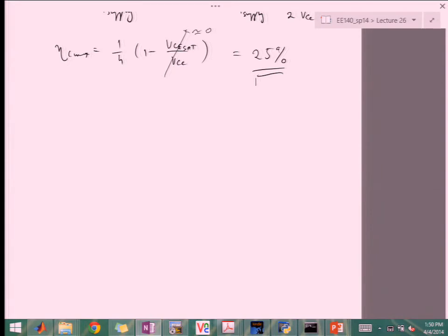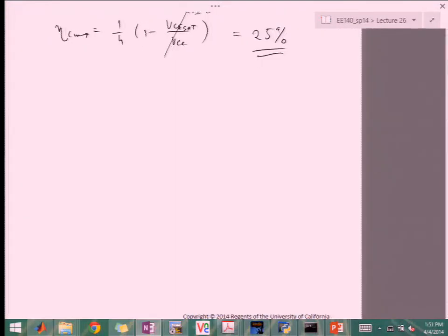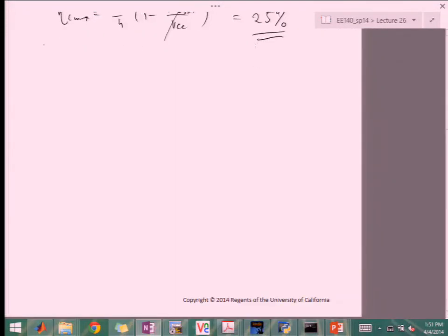Another very important aspect in terms of preventing things from blowing up in the lab and in life is to look not only at the power you deliver to the load, but at what power is being absorbed or dissipated in the device that actually delivers the power. If we look at the waveforms, we can figure out the maximum for that as well.